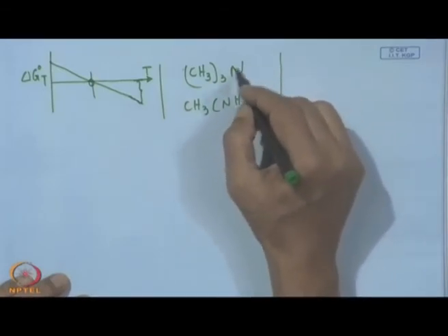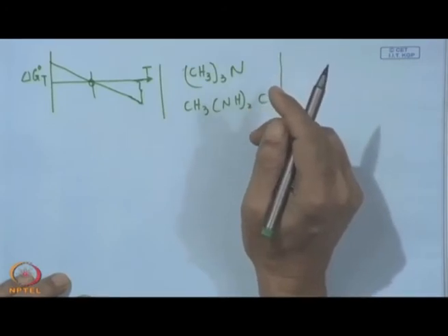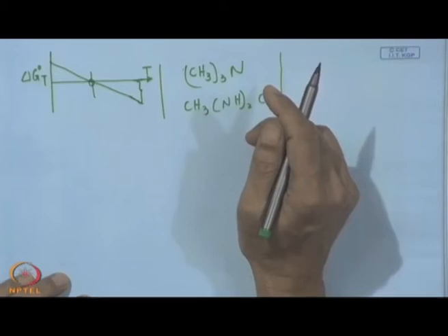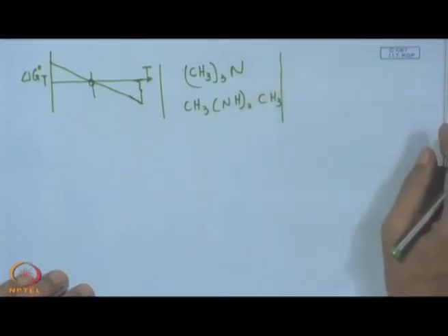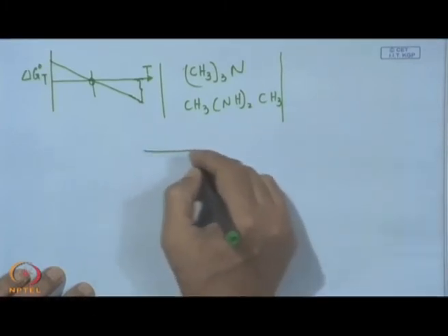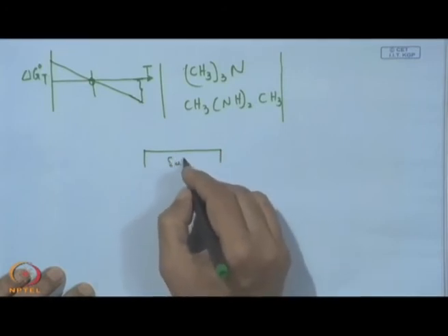However, if we cross that limit, what can happen is that instead of heterogeneous reaction, we may end up with homogeneous reaction. One precondition of CVD for all this coating process is that the coating should be synthesized on the substrate.